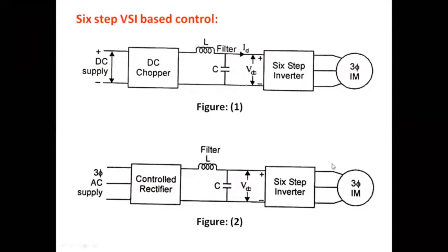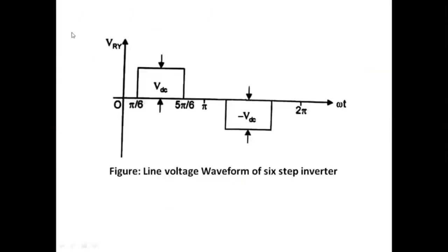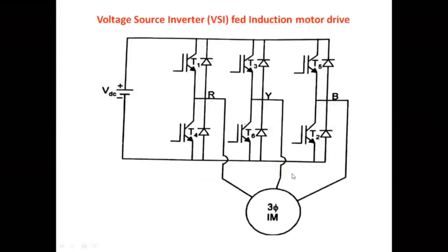The output voltage is also controlled by means of the variable input voltage, and the frequency is controlled internally. Variable voltage, variable frequency is obtained at this terminal. So I can control the induction motor here under constant V by F. This is when the inverter operates in 6-step mode, providing direct firing angles instead of pulse width modulated control.